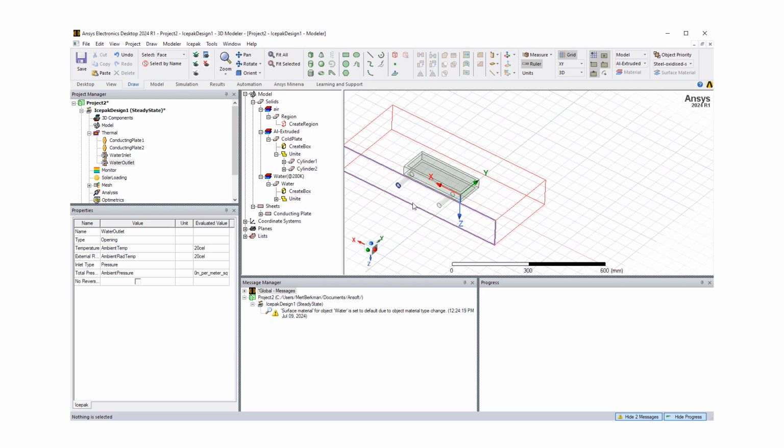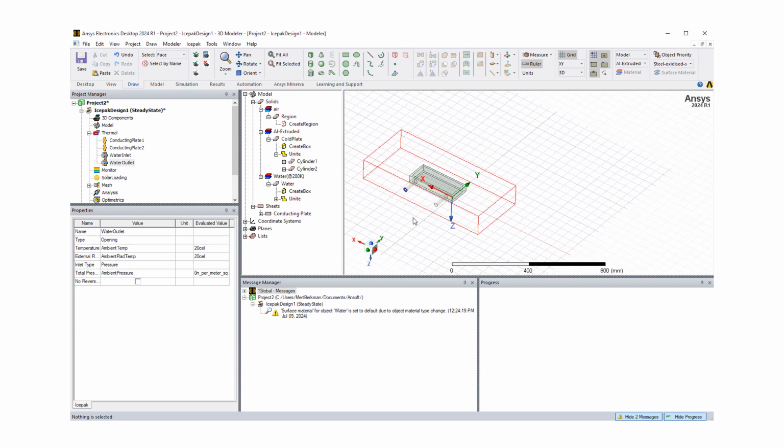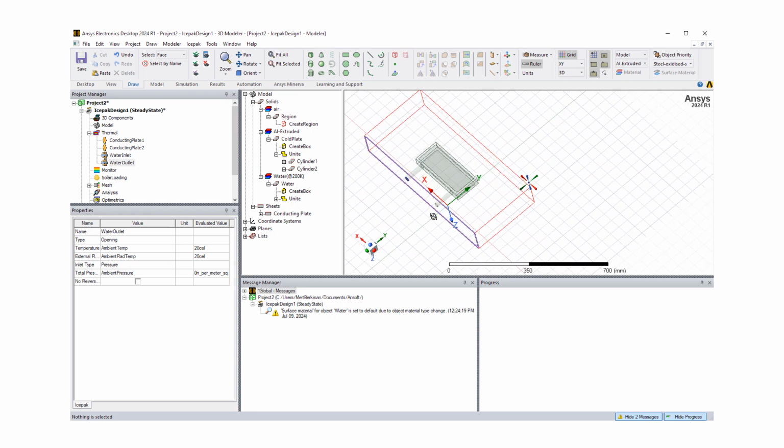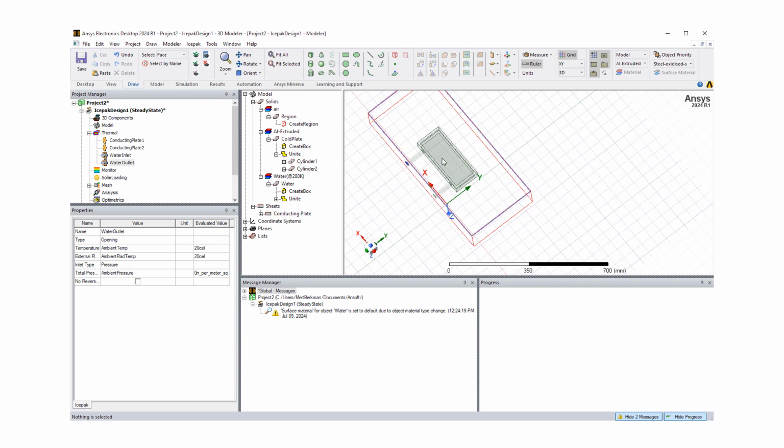What we're going to do is whatever wall or boundary we do not define, it's going to be turned into an adiabatic wall. In this particular case, we're going to have some natural convection flow, and gravity is in the negative x direction.